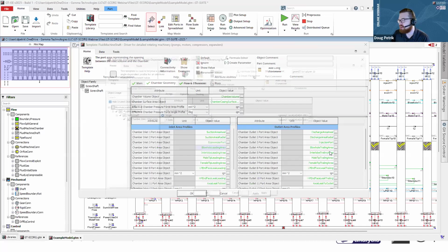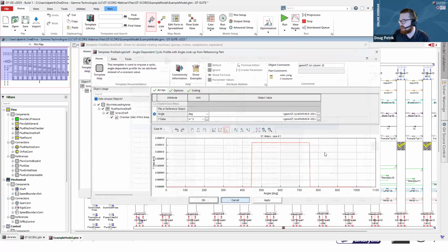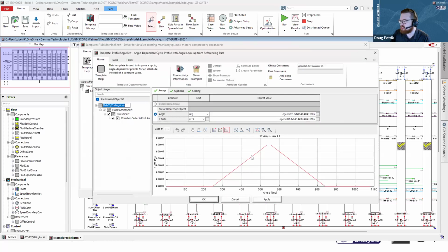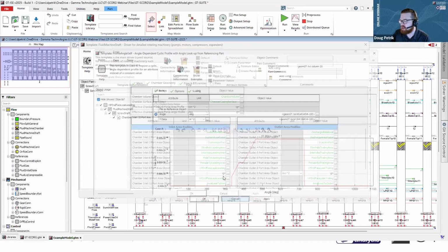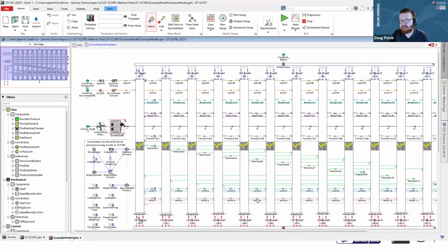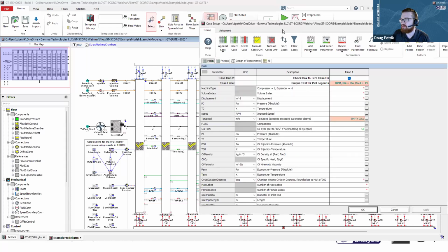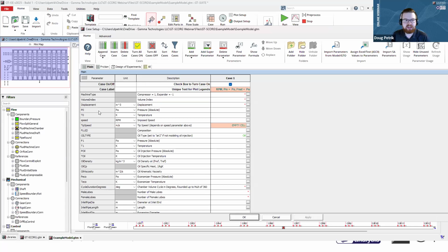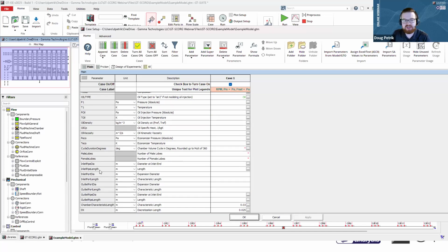So you can see all here's the blowhole leakage and the timing, the tip trailing leakage, the face leakages as well. And the entire model is linked up and connected for you. All you need to do is go to case setup and start supplying your boundary conditions. So that would be pressures, temperatures, speed, if there's any oil injection, the pressure of the oil and the temperature of the oil along with the viscosity, and as well as maybe some geometry for the inlet and outlet piping.